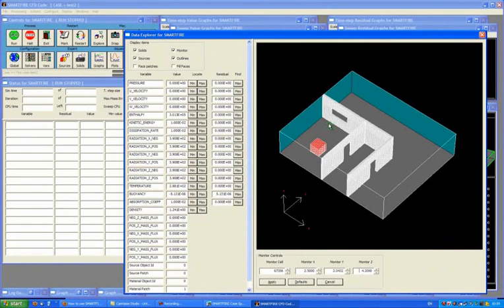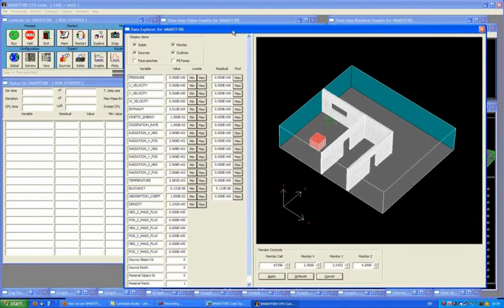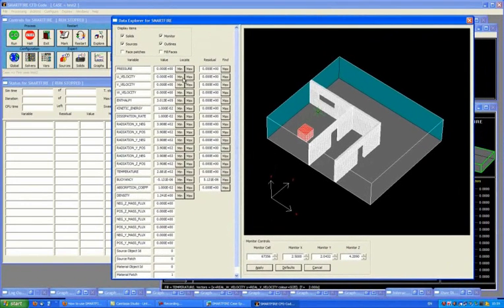The particular cell that is selected will have all of the values that have been calculated available, including the residual inside that cell. This menu is particularly helpful as well because you can select to see min and maximum values in such a way that the system will search for the cell where there is the minimum or maximum of a particular variable.